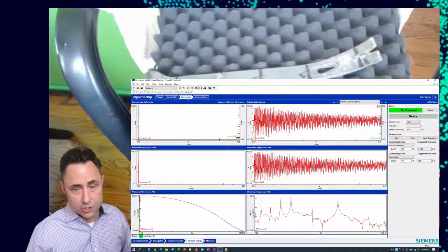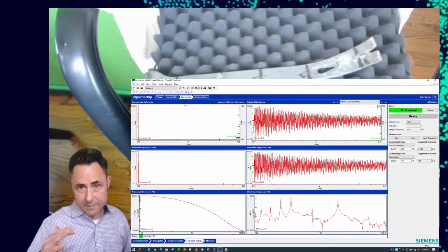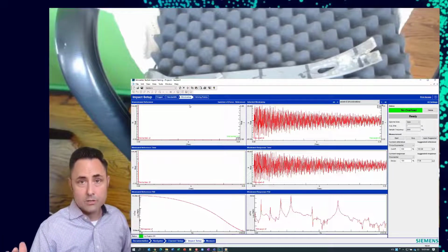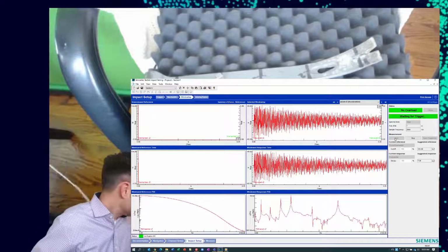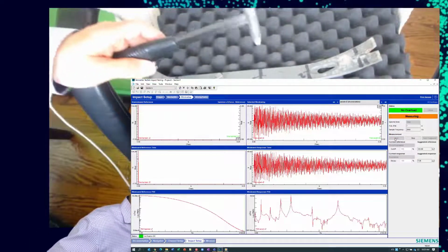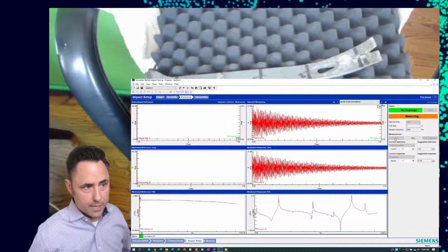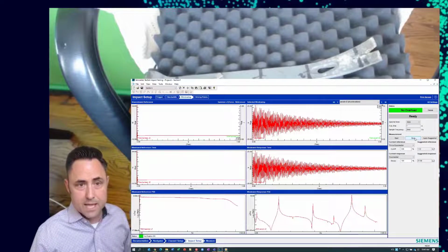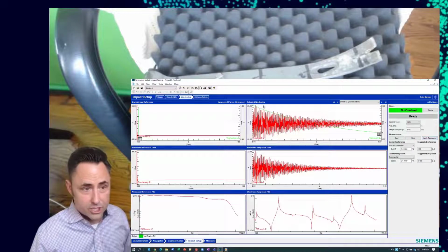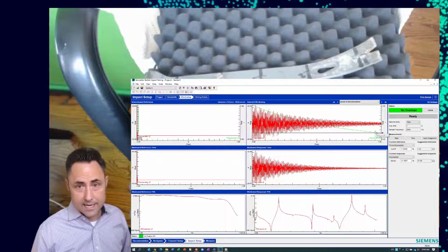Windowing, and this is going to make sure that my structure is no longer vibrating or still oscillating back and forth at the end of my time window, otherwise I'm going to suffer from leakage. And so I'm going to again start. It's going to tell me to take a measurement, and you see the unwindowed version up here. I'm going to stop even after one hit, and I'm going to apply those suggestions, and you see it's applying this force exponential window to make sure my structure is nice and died out by the end.